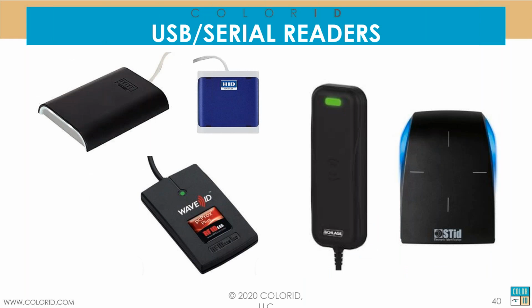And if you find out that the reader that's embedded, or maybe it doesn't have an embedded reader for your card types, then you can buy a lot of different kinds of card readers with wires coming out of them. And they can be USB, they can end in RS-232, they can be RJ45 to carry serial data through what looks like a Cat5 port. These are very capable readers. They can convert a lot of different card data into what will work on a machine like a point of sale machine or a printer. But it takes some experience and it takes some experimentation. Once you figure it out, you're all set.